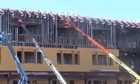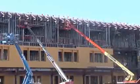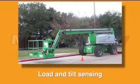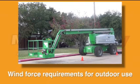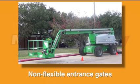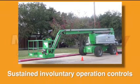Additional safety design features are now required on all new MEWPs. New safety features include load and tilt sensing, stability tests for pneumatic tires, wind force requirements for outdoor use, toe boards on all platform areas, non-flexible entrance gates, taller platform railings that meet OSHA and ANSI requirements, and sustained involuntary operation controls.